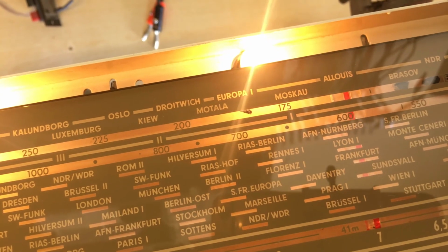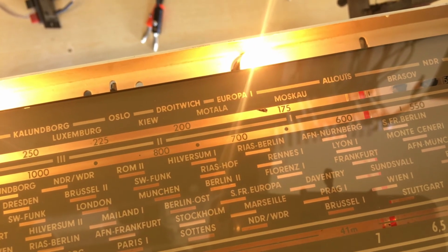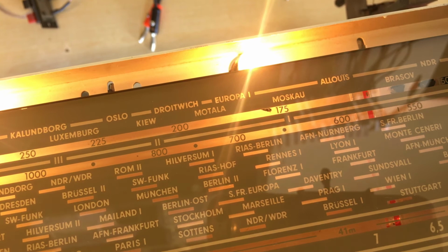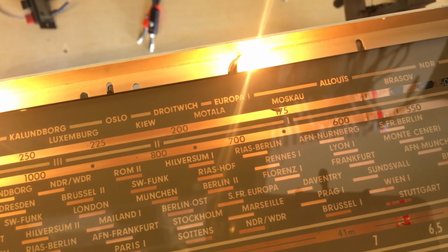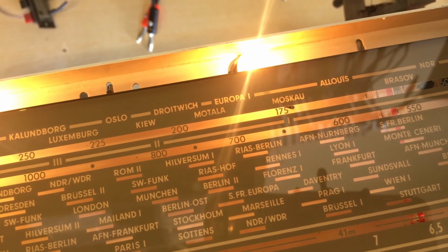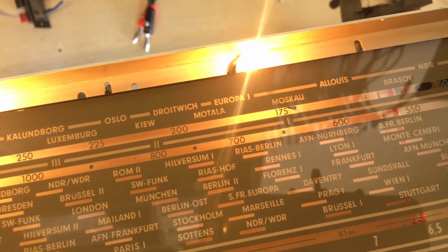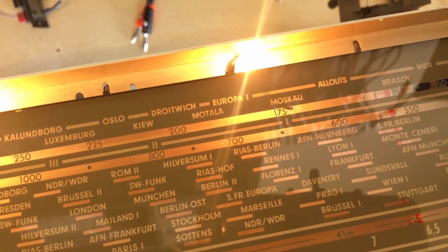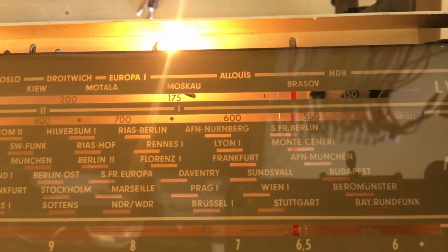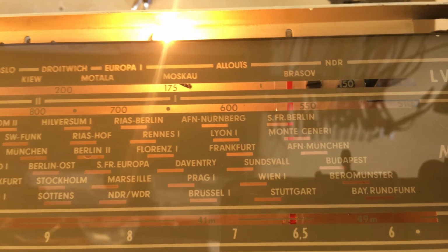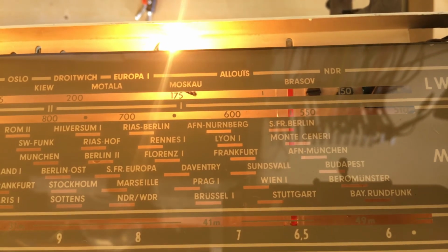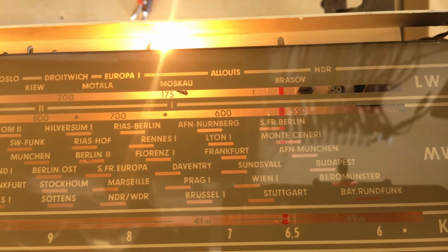So we've got the generator at 560 and we're going up. There it is. I'm looking at the meter. That's my peak on the meter, and where is it on here? Near as damn it, it's slap on. So that is done. The medium wave RF alignment is done.